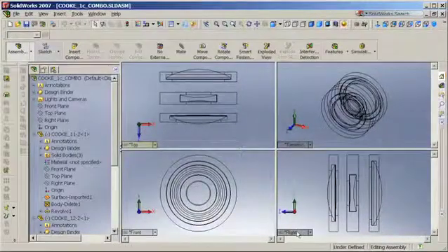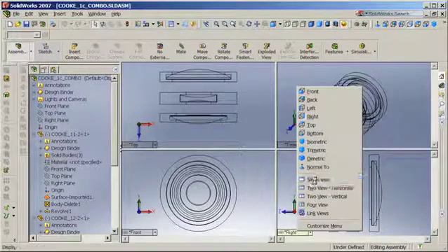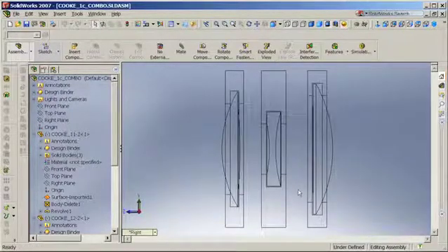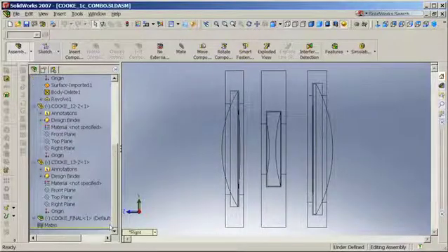Okay, so here's the file in SolidWorks, and again, let's expand this view to get a better idea of what's happening. What we have are our mounts, our retaining rings around our lenses. We also have our lenses. Now, as a general rule, you don't want to export these optical components from the CAD program as an IGES or a CAD format file, because your lens design program and the ASAP translation understands optical surfaces generally better than the CAD programs do, so there's going to be less approximation if you use the files directly from the lens program. I only needed these lenses so that I could build the mechanical structure.